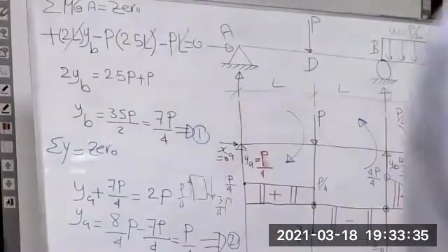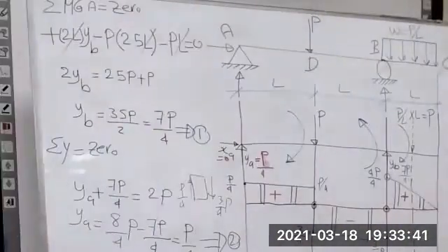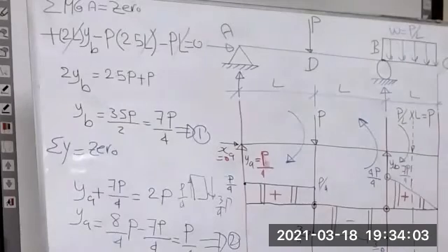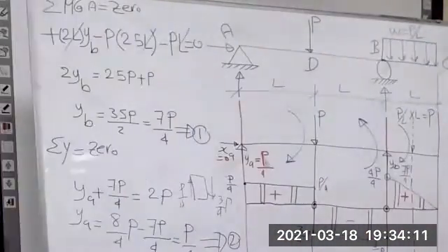Asking you about the maximum shear, I have to tell you what the maximum shear is. W is per unit length. Here, W equals B over L. That is per unit length. Yes, this W is per unit length. Yes, this is a uniform load. What is the maximum vertical shear force if W equals B over L? He gives you the condition. Now, what is the maximum internal shear force?